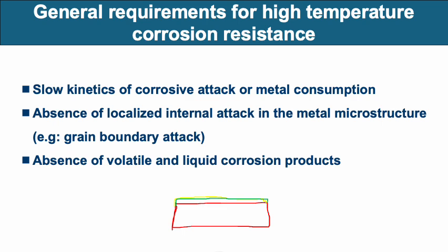And this develops an oxide film or a scale, because in this context we should really call it scale, because these are thick. These are not the nanometric scale films that we talked about in passivity. These are sometimes 5-10 microns thick. So if this forms a protective scale, a solid scale that prevents further penetration of oxygen, then I am safe.